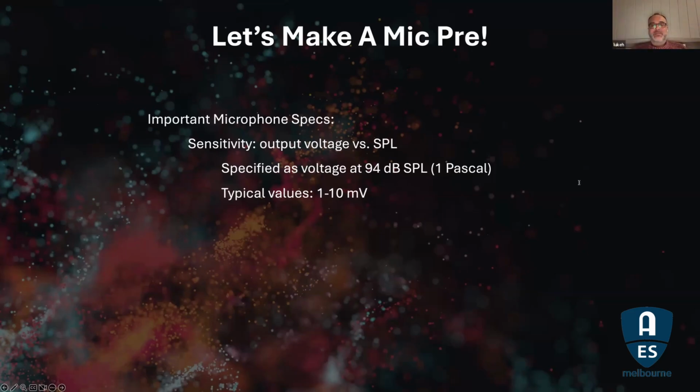So that might be worth a bit of research on our part to see if there's something cheaper and better. Well, I don't know about cheaper, but the 1612 may not be the right part for that because it's not terribly well optimized for current noise. They run huge amounts of current through the input transistors, which gives you nice low voltage noise. But the side effect is they're pretty lousy for current noise. There's a fair amount of current coming out of the part, basically.